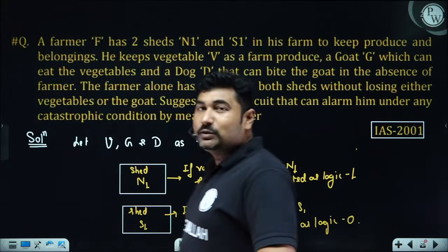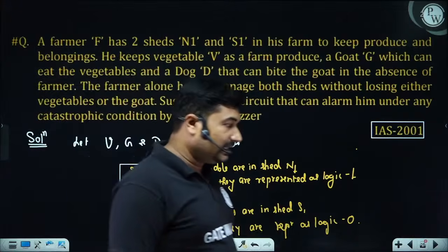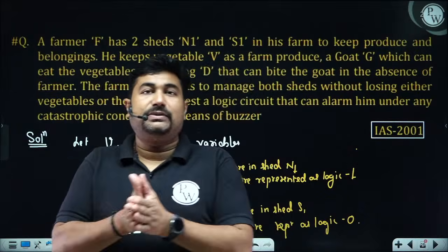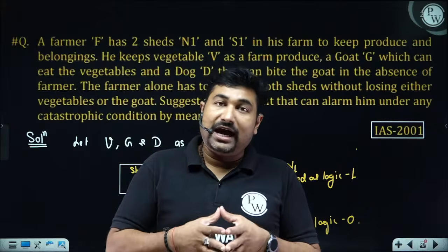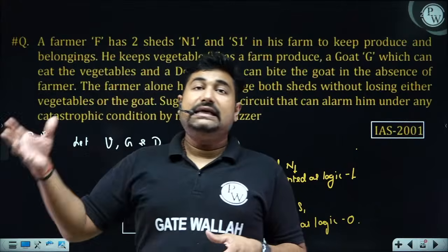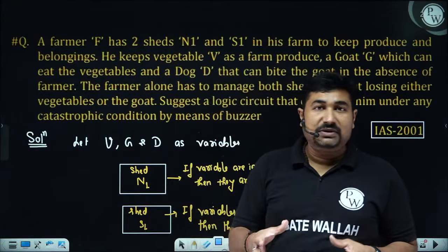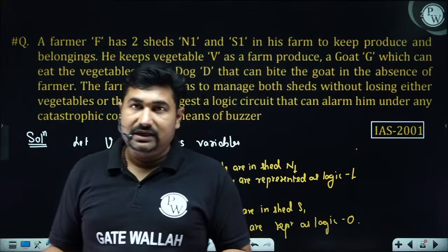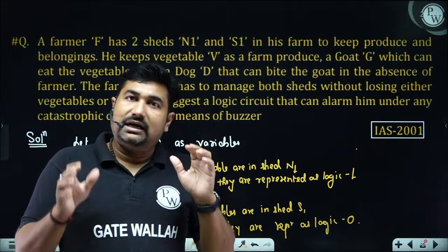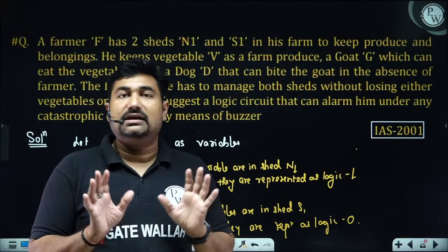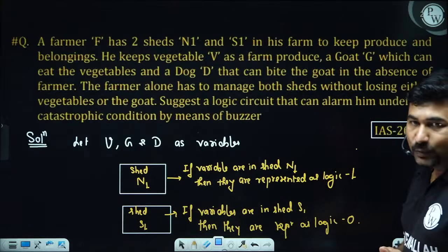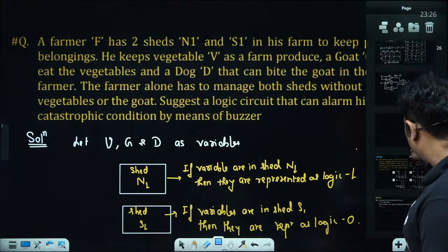Great. Hoping you are able to understand the K-map well. The conclusion is always to first find the EPIs along with the preferences. Don't care: you have to select the logic of don't care such that it helps in minimizing the logical expression. In the same K-map, some of the don't cares may be logic 0 and some may be logic 1. There is no issue. Ultimately, they will help to minimize the logical expression in the K-map. Is it okay? Great. Hoping all of you are able to understand this question well, beta ji.